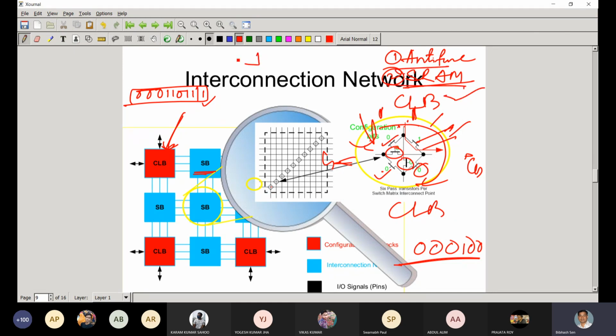In anti-fuse, two wires are connected in this way. When you short this line, the bit will go in this way. In fuse technology, when an overvoltage is applied, the circuit is disconnected; the fuse breaks the circuit. Here, in the anti-fuse, when a voltage is applied, it actually connects the two terminals. That's why it is called anti-fuse technique. Is it clear why it is called anti-fuse?